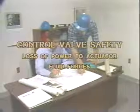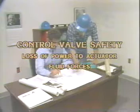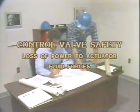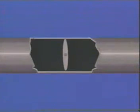Another consideration is how fluid forces will affect the valve in the event of a mechanical failure. Should fluid forces tend to open the valve? Or should fluid forces tend to shut the valve? As you can see, the concerns will be similar to those for a loss of control signal or actuating power. More information on how the various valve types are affected by fluid forces is included in the text.